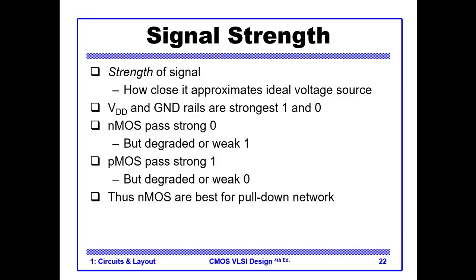So, signal strength. What is signal strength? Signal strength means how close it approximates the ideal voltages, and by ideal voltages we mean the logic thresholds that we defined previously: VIL, VIH, VOL, VOH. So how close is your signal to these voltage ranges?